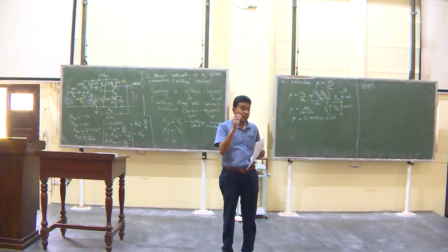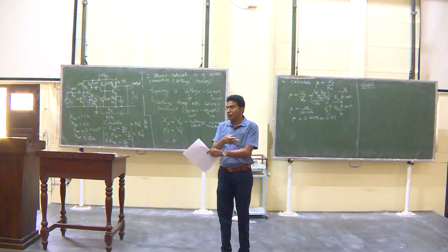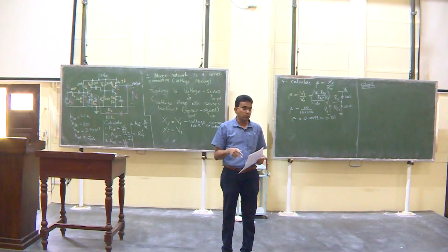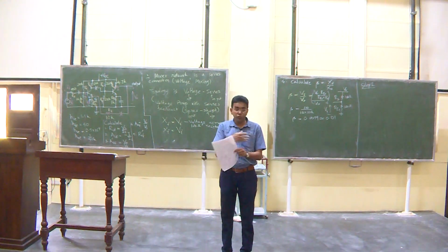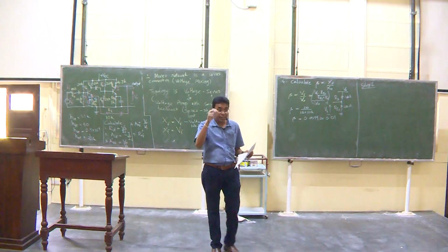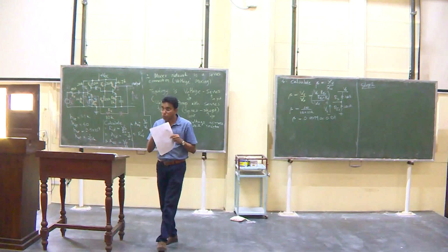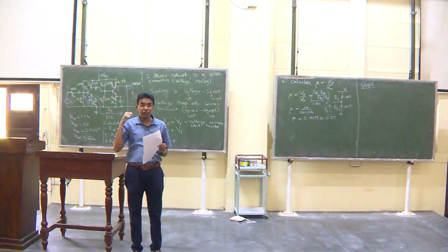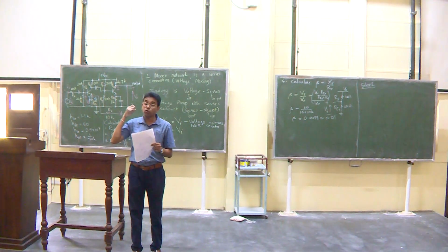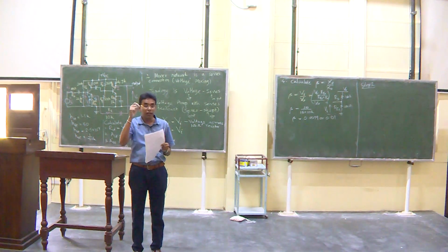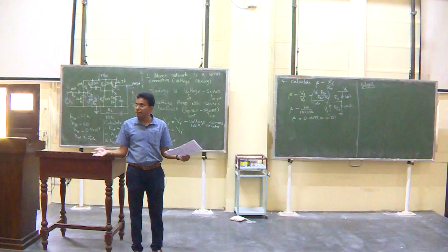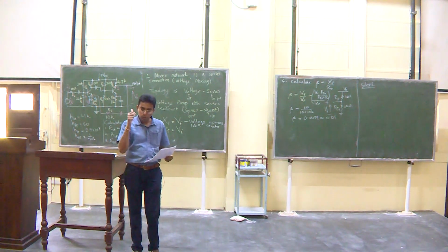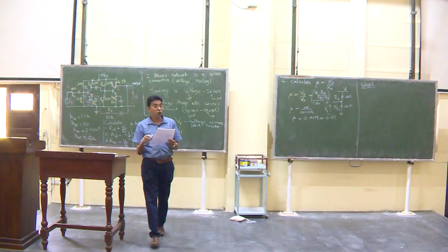Because if we wrongly identify an input as a voltage when it is a current, all your parameters will be wrong. If you identify your output as a current instead of a voltage, then your parameters will be wrong. You will be defining XFs and XIs and XOUTs wrongly. So, it is very important to identify this, and also very important to identify beta. If you have beta wrong, 1 plus beta A is going to be wrong anyways, right? So, all these steps are important in order to make sure your answer is going to be correct.